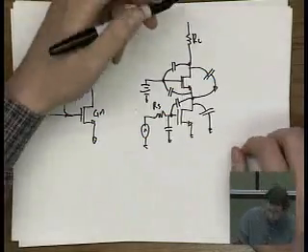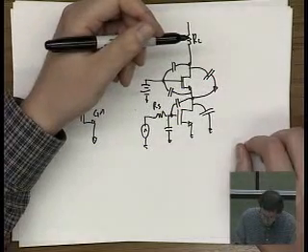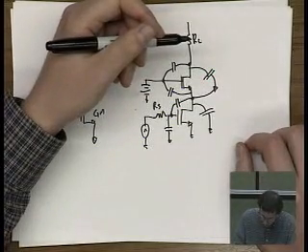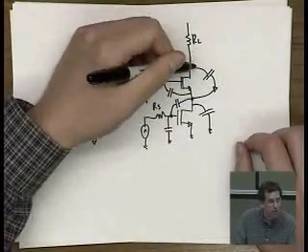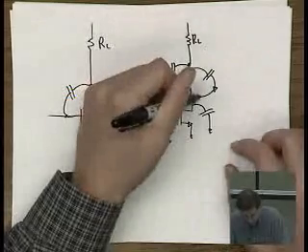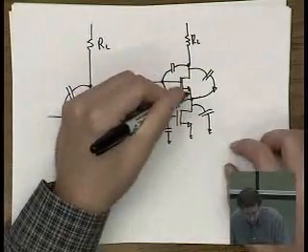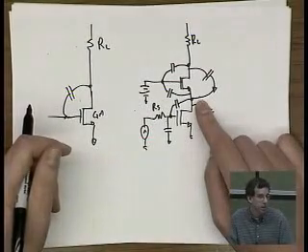Is there a Miller effect present? That's a good question. Not really, actually, because it's positive gain from point A to point B. And the other thing is that this node here is a low impedance node. It's 1 over GM, right?